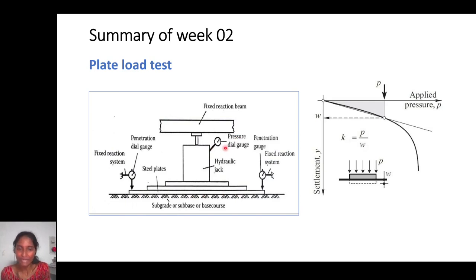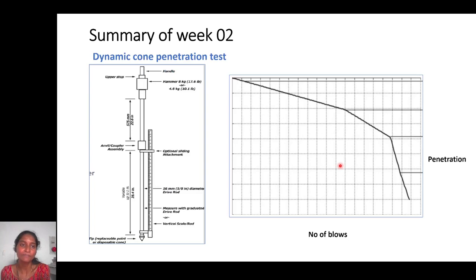That is your aim here. If you know that pressure, and we know the deflection we are taking is 1.25 mm, then the ratio will be the subgrade reaction. Mostly the subgrade reaction can be used to determine the strength of the subgrade layers. This will also be used in concrete pavements for other purposes, but here we mostly use it to understand the strength of the subgrade.